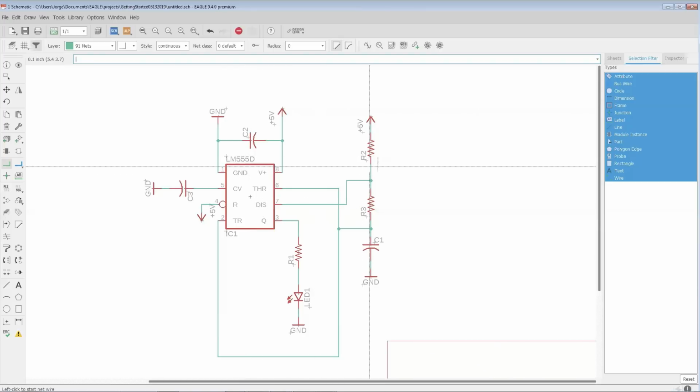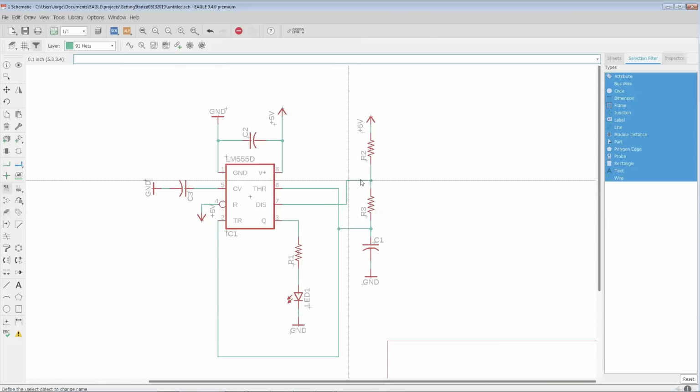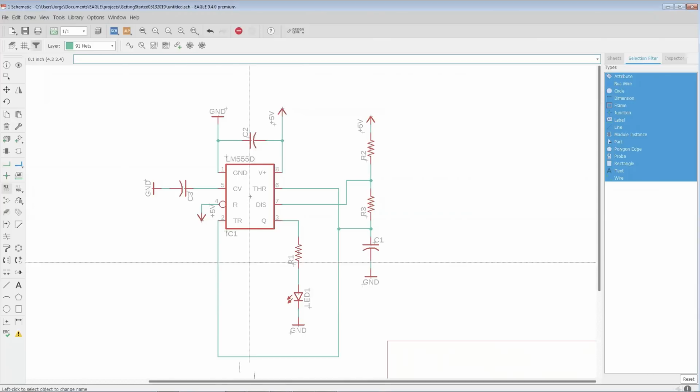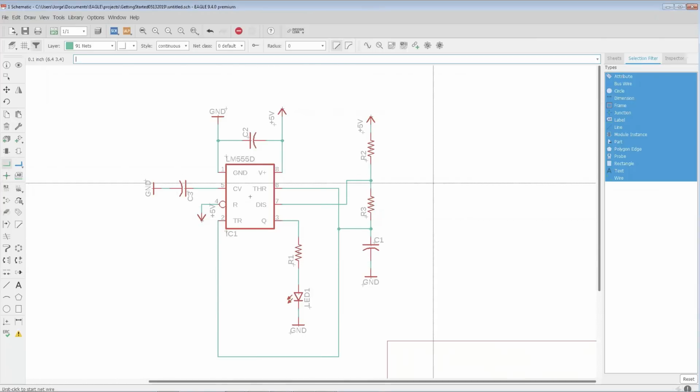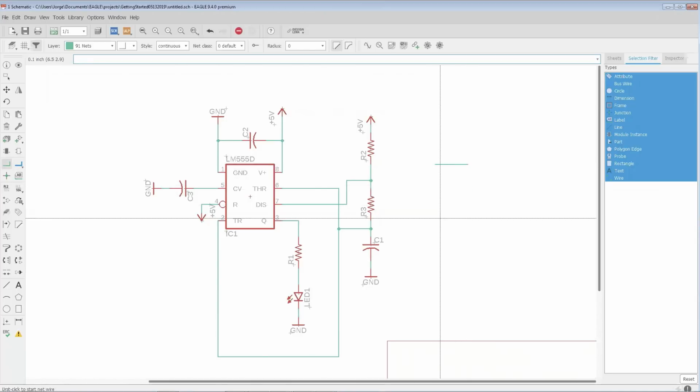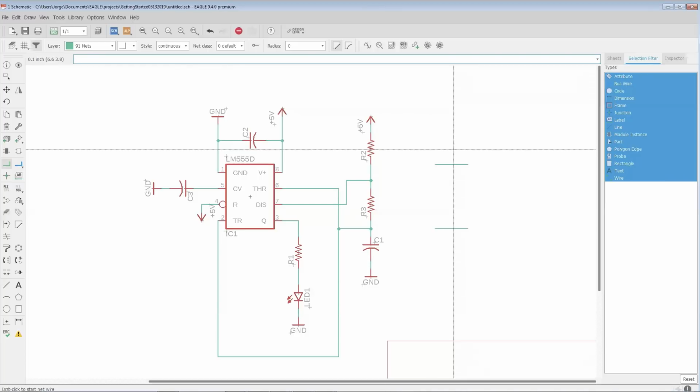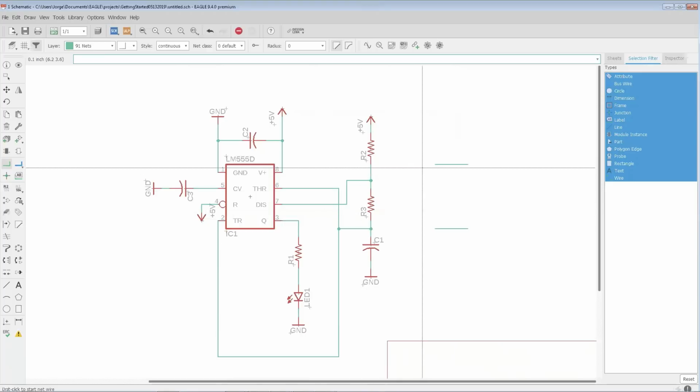That brings us to a very important point in Eagle. All connections in Eagle are defined by net name. If we look at the name command, you'll notice that every trace has a name. Every single one. Whenever two nets have the same name, they're automatically connected. So if you have a very dense design, you can have a stub here and a stub here. As long as they have the same name, they're considered to be connected. That comes in handy when you're breaking out 1,000-pin BGAs or very high pin count components. It's easier than trying to do point-to-point connections drawing the different items.